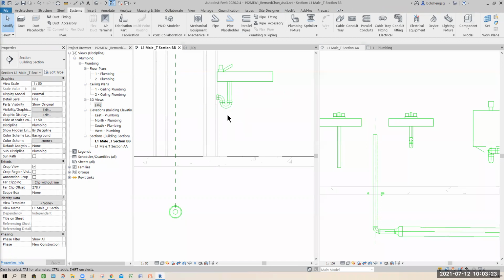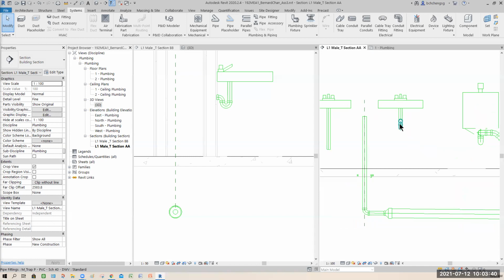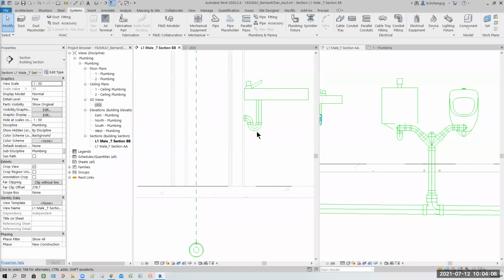Okay, now from here to here, or connecting to here, is similar to what you are doing. But I want to show you something interesting, since we have the advantage that they are both identical and the height is the same. So I want to do something unique because I mentioned before, if based on this the water goes straight, sometimes if the flow is not fast enough, it flows back, agree? So here, no matter what, there must be a slope. But what if I introduce another trap here? It means an S like this, then go up.